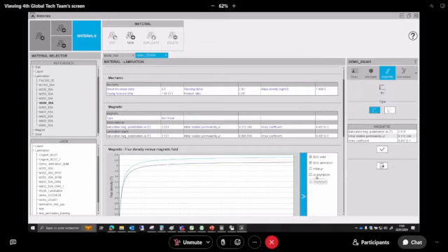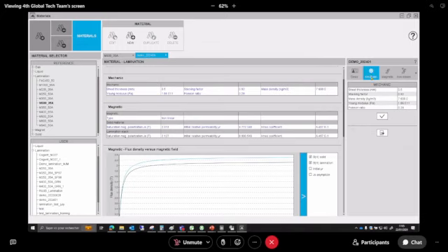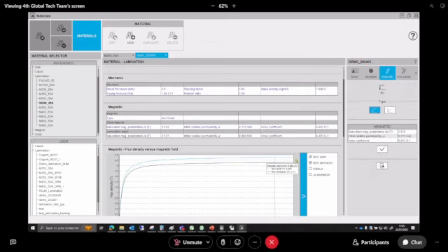Same thing, something you have to know is that the material you imported is the blue one, and depending on the stacking factor you used, Flux Motor will use the dark one because it takes into account the impact of the lamination on the initial BH curve you have.